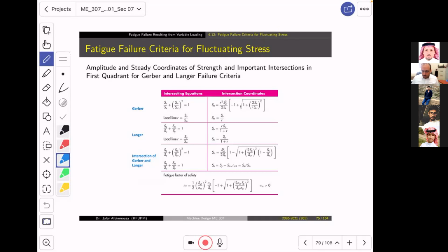The general wisdom is that we tell him, go look at the material, look at the yield stress, and then find the strain there or the load. If you apply, listen to me carefully, an R of -1, which means the maximum is the same as the minimum in magnitude but with negative sign, as an amplitude, if you apply the yield load as an amplitude, you will probably get no more than 1,000 cycles. No more than 1,000 cycles.